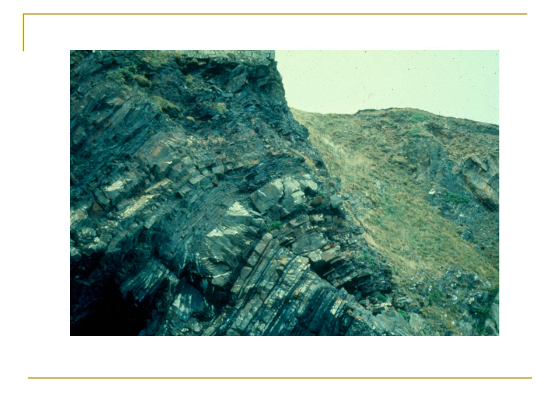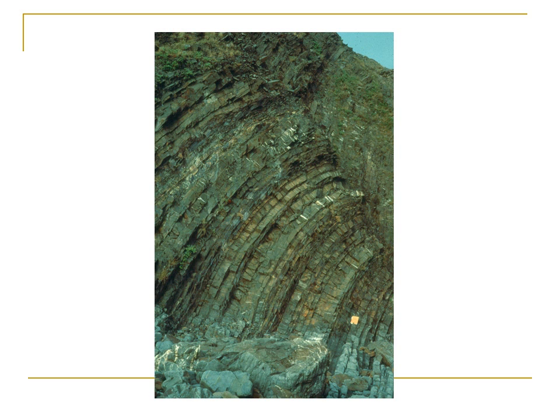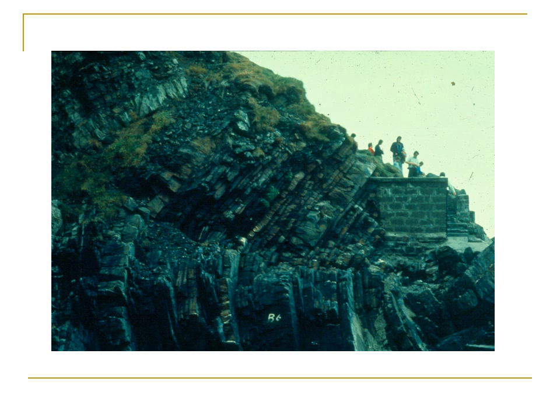Here's some examples from the field where discontinuities are dipping into the slope face, but a potential sliding mass is already forming and has the ability to move further down the slope. Here's another example where closely spaced discontinuities help to define potential topple. And there you'll see in the bottom right a field notebook for scale to help you see how big this sliding mass is. Here's another case of toppling from a quarry in Wales.